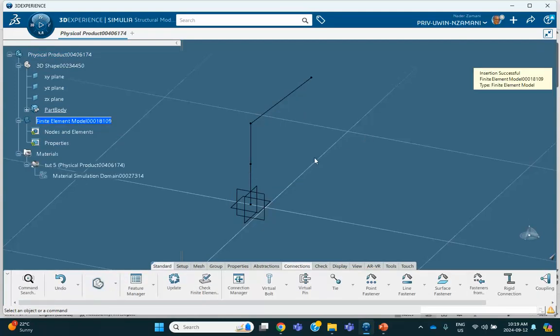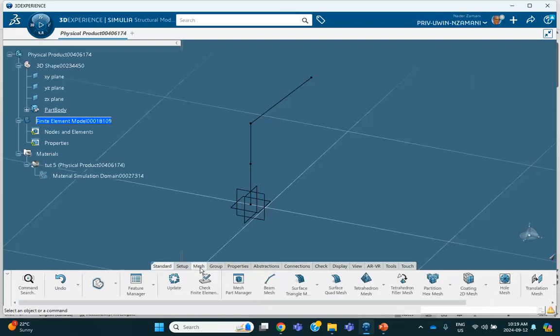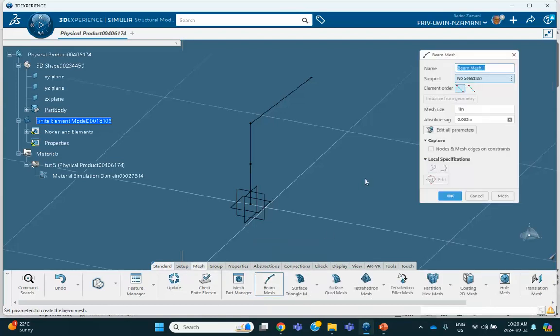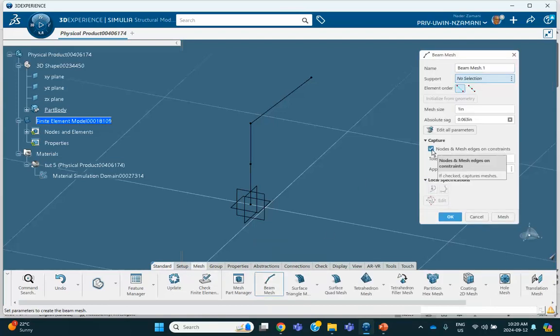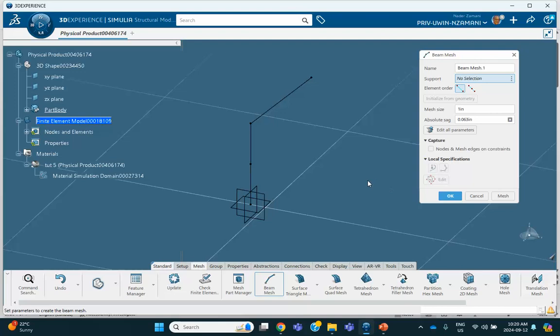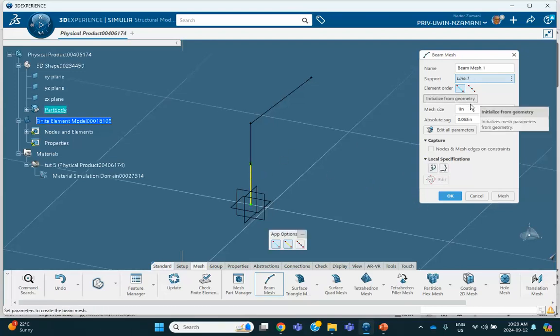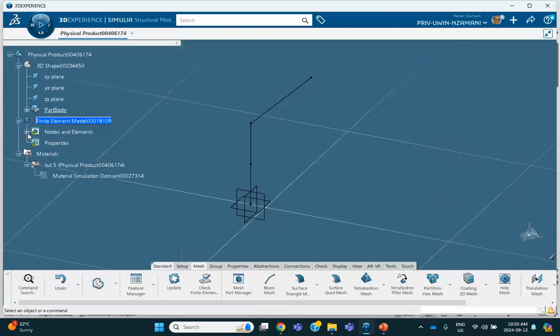All right. So here's the meshing tab right there. Here's the beam mesher. You click on it. This box should be unchecked because otherwise any two nodes that are within certain tolerance are going to be merged. I don't want them merged. Okay, so I'll do this one first, and 1 inch element size. So linear, it's going to be 5 elements here, 5 elements there, and 10 elements there later on. So we say okay. Notice that this is created right there.